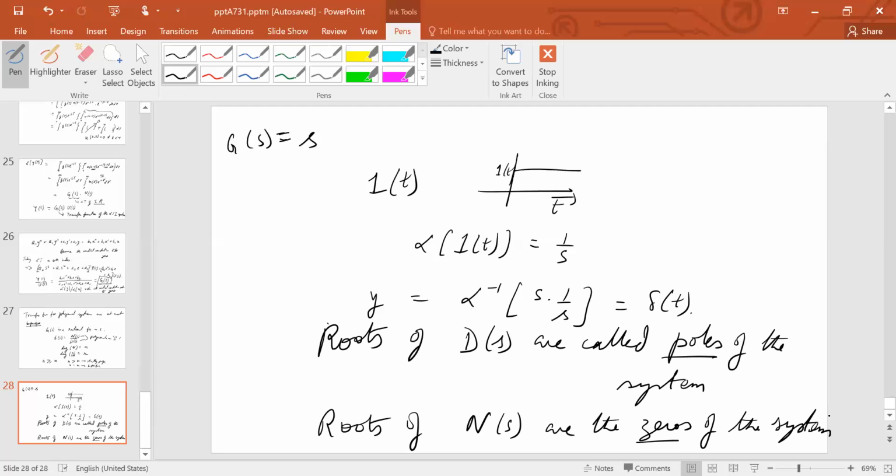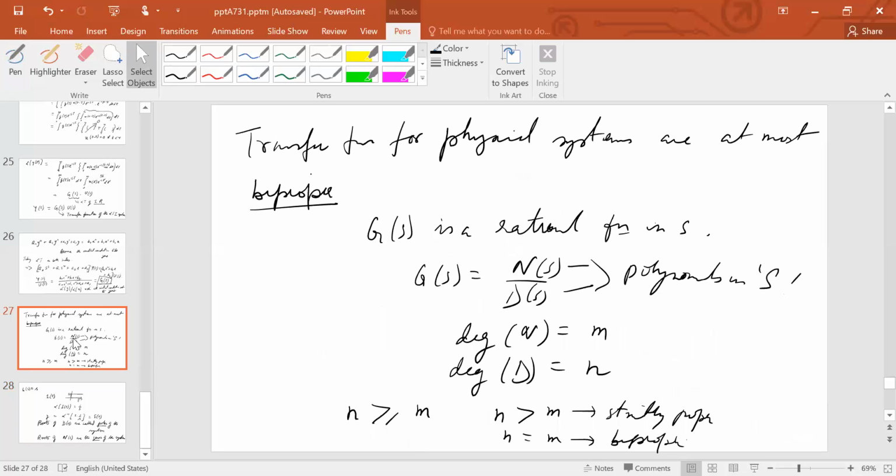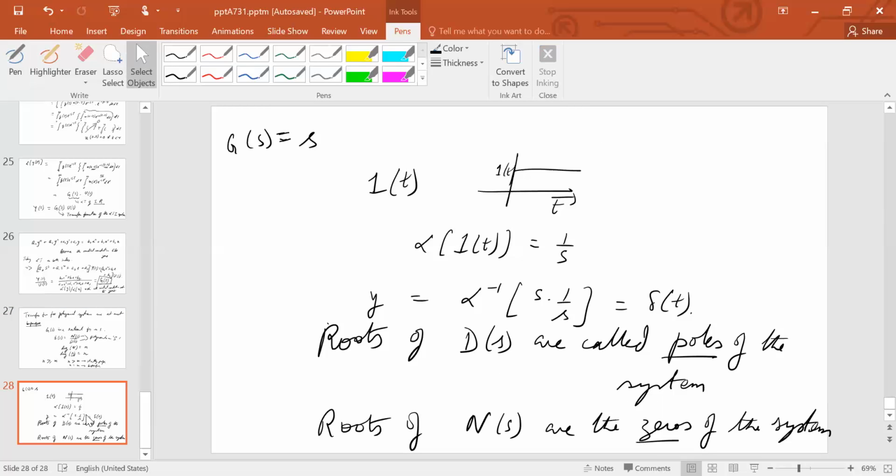And when you have already gotten the Laplace transform of the impulse response, which is the transfer function, then basically the system can be completely characterized by its poles and zeros, because what else do you need in order to characterize a polynomial but its roots? So therefore the overall behavior of a system can be studied if you understand where the poles and the zeros of the system lie, right?